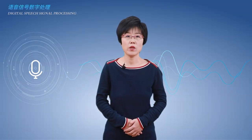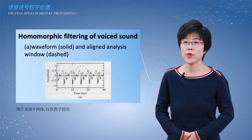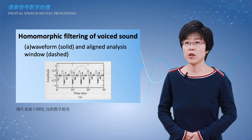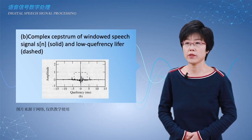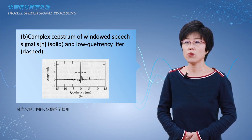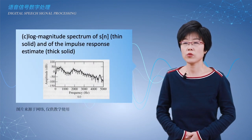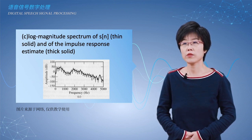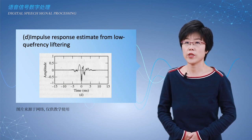Here is an example of homomorphic filtering of voiced sound. Figure A shows the waveform, solid line, and aligned analysis window, dashed line. Figure B shows the complex spectrum of the windowed speech signal s[n], solid line, and the low frequency filter, dashed line. Figure C is the log magnitude spectrum of s[n], thin solid, and of the impulse response estimate, thick solid. Figure D shows the impulse response estimate from low frequency filtering.